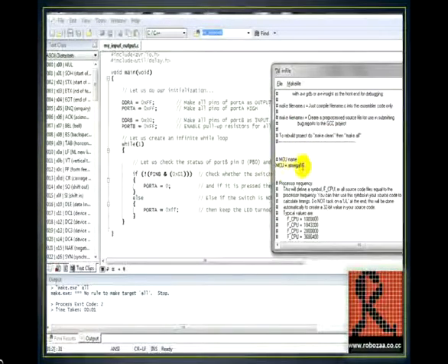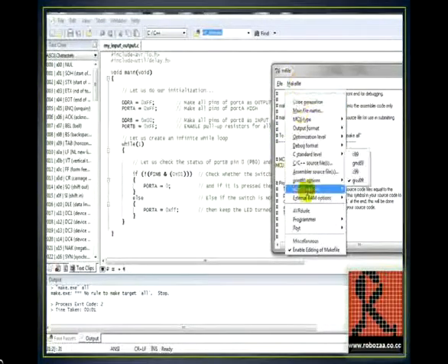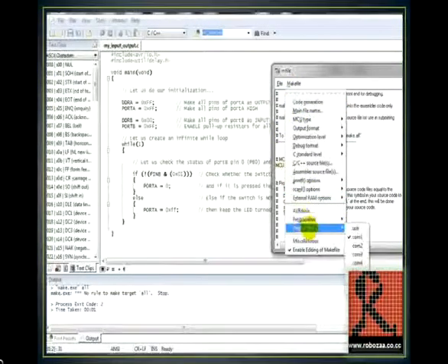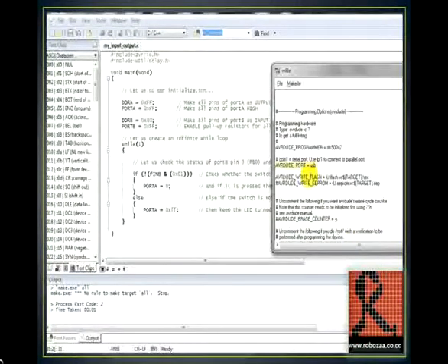Okay, MCU name has been changed. Now I need to configure the programming port to USB, and since I'm not using the STK500 V2 programmer, I have to edit that. I'm using a USBasp programmer, so I have to write usbasp in place of the AVR programmer,